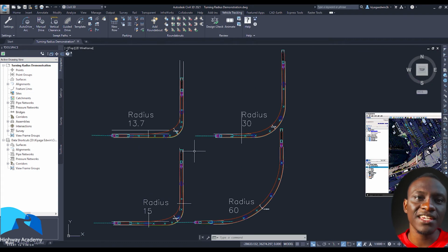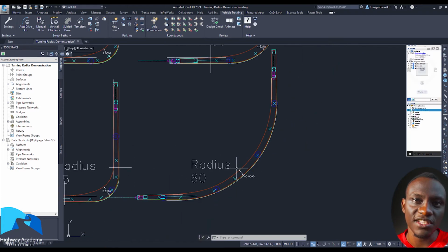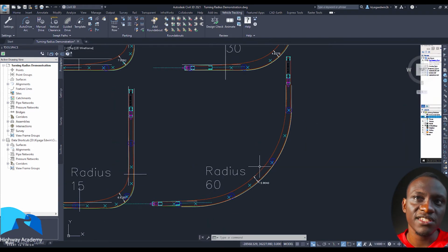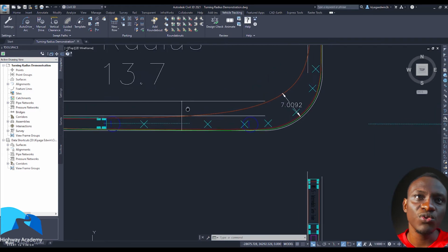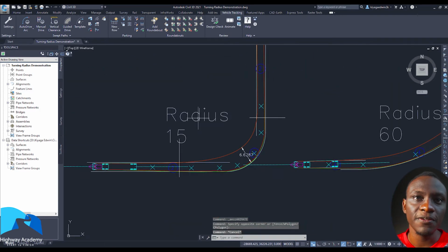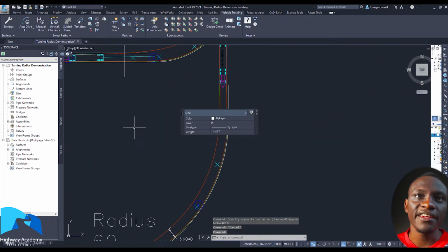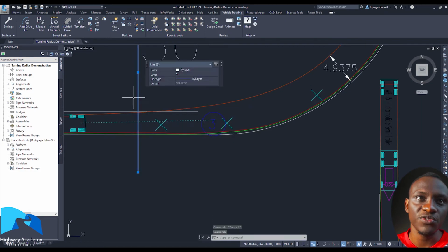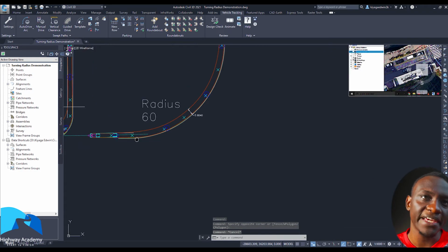So what you're noticing is the higher the radius, the less the width offset that you need. The challenge with that is you find that you need more right of way compared to this. And two is the different stop lines are at different areas. You find that's where the stop line would be. This is where the stop line for this would be. And this is where the stop line for this would be. And as a result, this keeps offsetting the stop line.